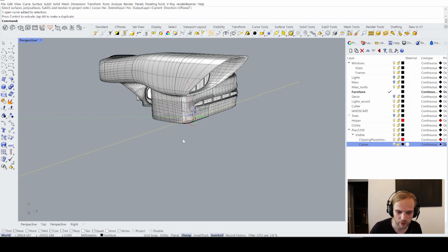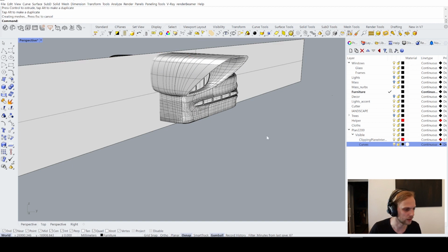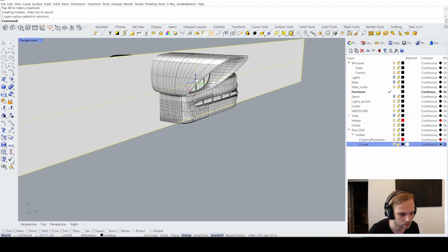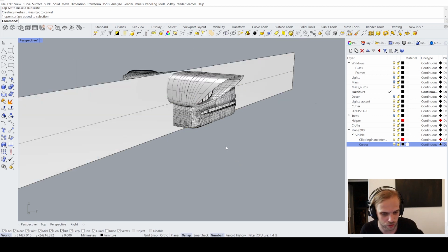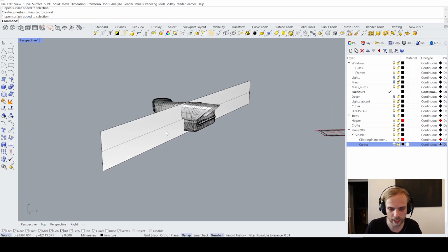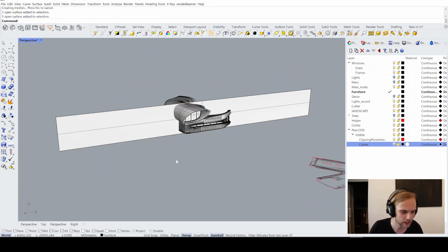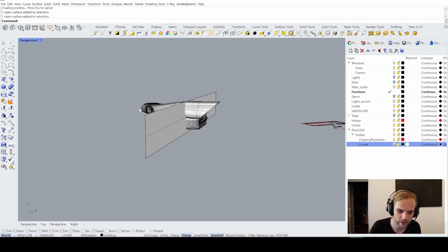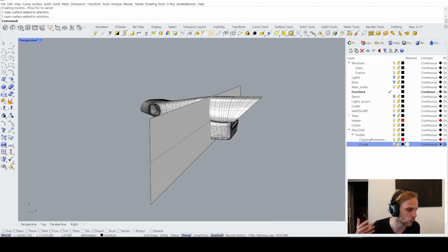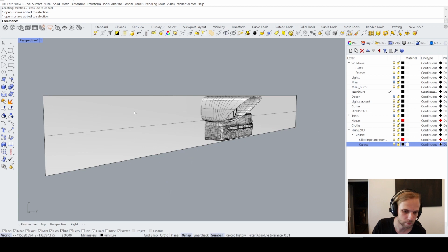Great. So now I'm going to just extrude it up like that. You can either use extrude or you can just, when you use the gumball, for every arrow, there is this kind of small bubble. If you drag on that bubble, it extrudes. So now we have ourselves a rectangle, right? A rectangle that cuts through where we want to have this section located. Next step is to actually create a clipping plane for it, right?